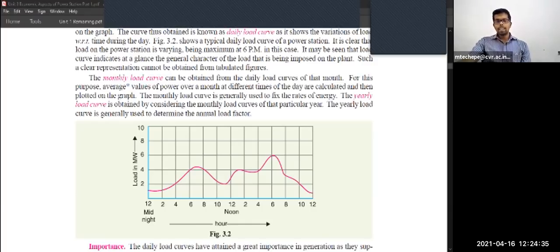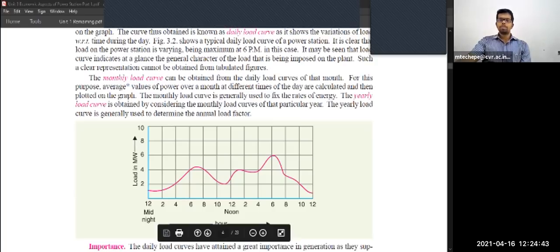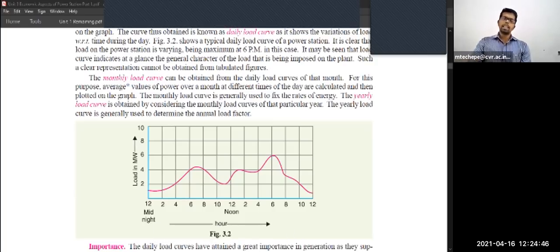As I already said, by knowing the load curve, in the substation they can predict the load. They might have the previous year's load for the whole Telangana state, the load on today's date. From seeing that load curve, they may predict this year 2021's load. It might be averagely 13,000, where the previous year was 13,300, so this year they might be generating some 200 or 500 megawatt extra.